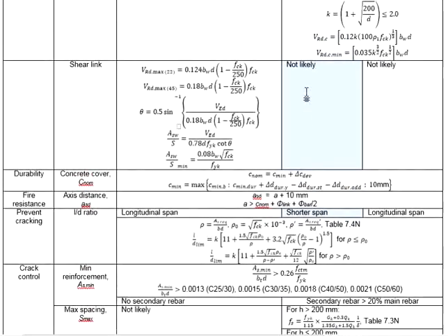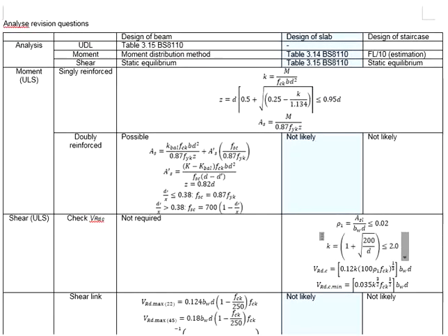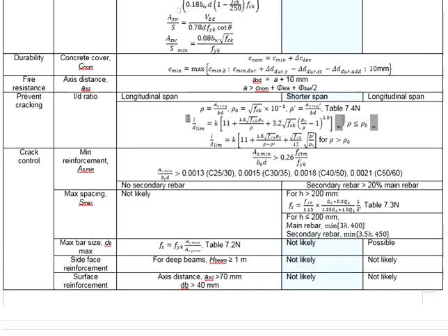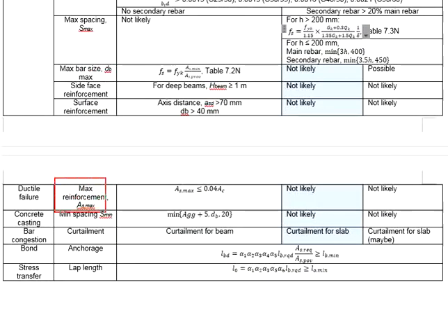If you observe the formulas in any other areas, most of the calculations will be on the basis of the effective cross-sectional area, such as when you calculate d, when you calculate VRd,c, when you calculate VRd,max, when you calculate As,min, and etc. It is only when you calculate As,max that you are using Ac, which is b times h. You are talking about the gross area of the structural element instead of the effective cross-sectional area.